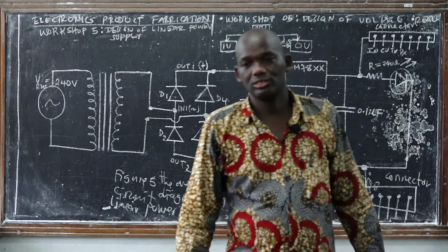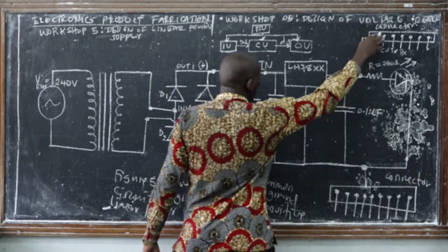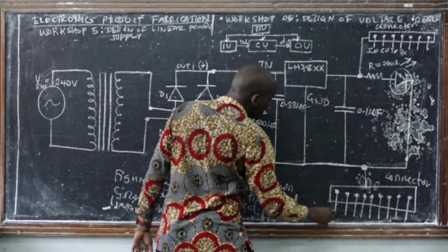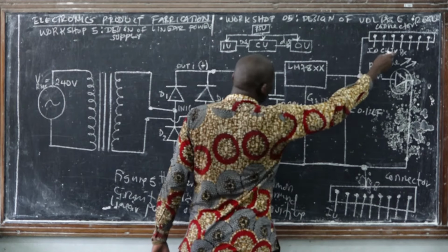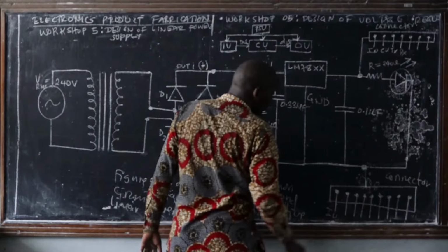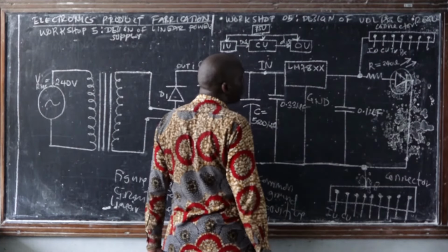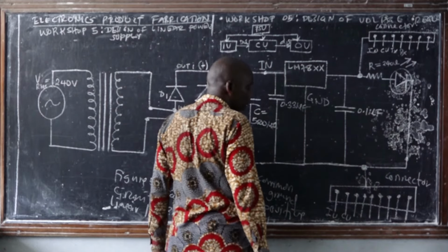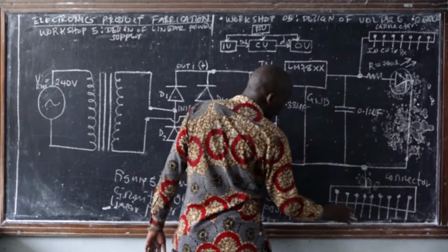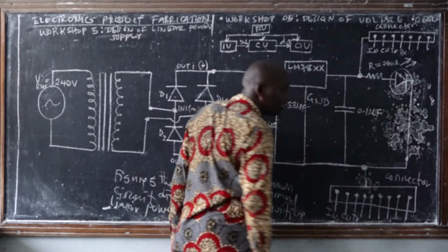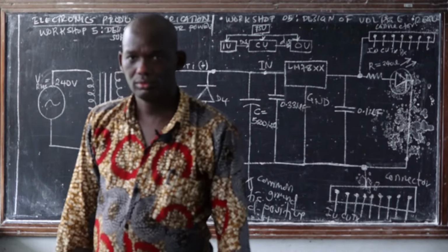So are we together? Yes. Good. So similarly, if we take this input supply or the power to the input unit, we also need to take its corresponding ground terminal. Again, if you use this terminal to provide the positive power to the control unit, then here we are going to have the control unit connected to the common ground. If again here we have a positive power fed to the transmitter, you also need the common ground to be fed to the transmitter. So that's the process.